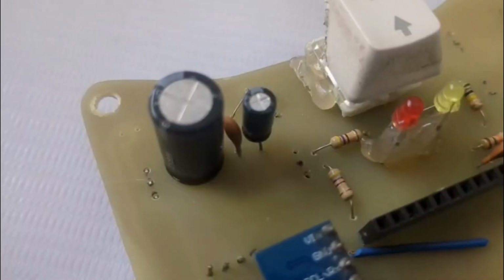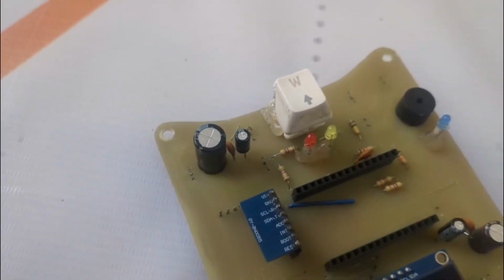We learned from our earlier versions that noise was a big problem, especially from the servos. So this revision is packed with decoupling capacitors all over the board to keep power clean and stable, not all of which are populated. On the schematic, nearly every pin of the ESP32 is used. Up top, you'll see the buck converter, indicator LEDs, and basically all our inputs and outputs are neatly organized. A MOSFET allows us to turn the IR LEDs off when needed.